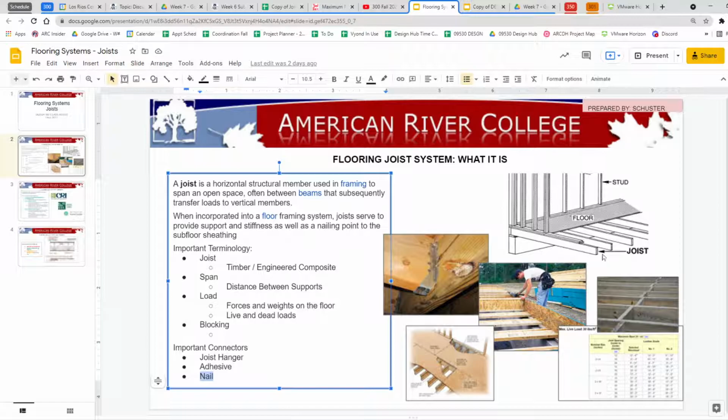When you put these joists in, you have to look at the wood and see which direction the grain is so that your nails don't split the grain under load. They are actually held by the grain under load. So you actually have to look at the grain on a joist to make sure that it's good.